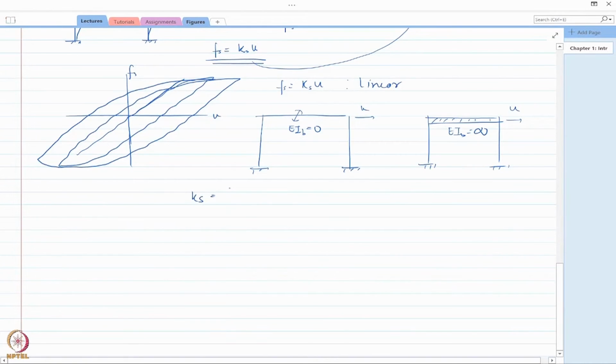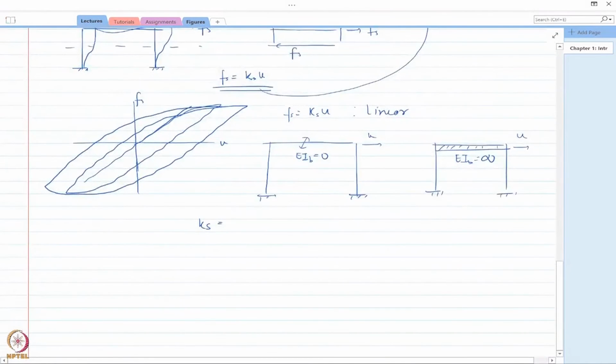As you can imagine, if there is no flexural rigidity here, if the column wants to bend, there is nothing to prevent that rotation. So it would be just the displacement you are applying like this, and the columns, or let's try it again here, the column looks simply like this, because there is no restraint on rotation here. So it would look something like this. In this case, because it is so rigid, these columns cannot rotate at these points. So the deformed shape would look like this.